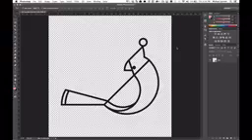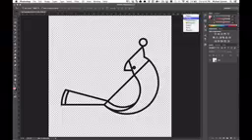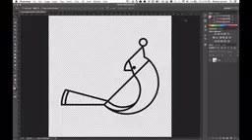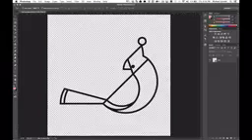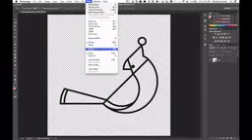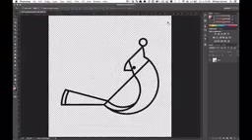You should have the birdpendant.psd file open. Before you start, be sure to change your ruler's unit of measure to either inches, centimeters, or millimeters, whichever you prefer. This makes it easier as we'll be doing some resizing, and it helps to use the same units that the printed object will be measured in. If you don't see your rulers, choose View, Rulers. Right-click on the ruler to select its unit of measurement.